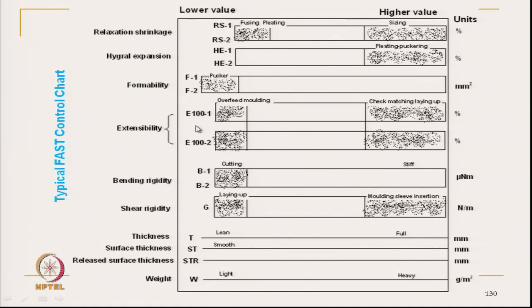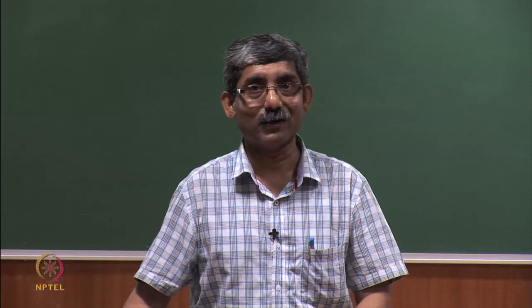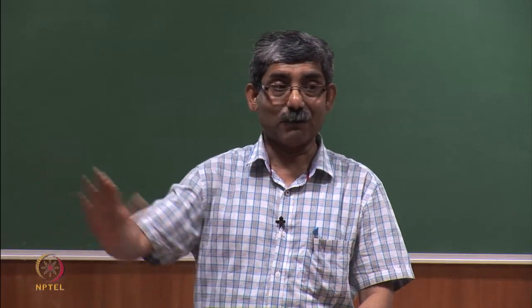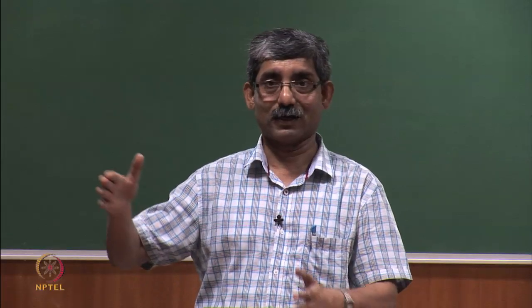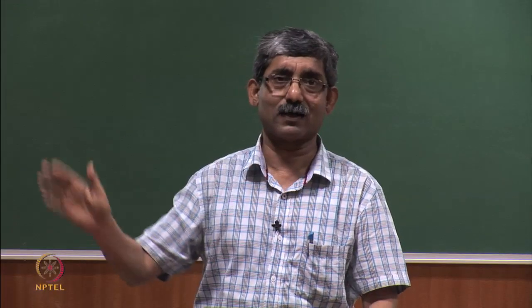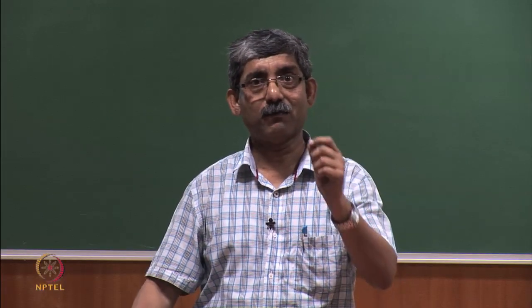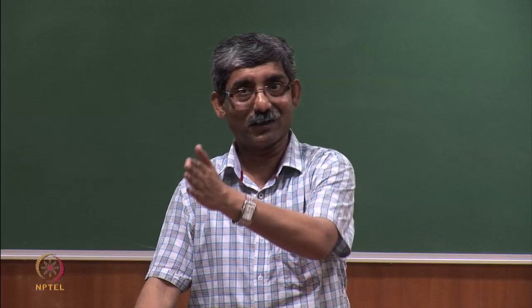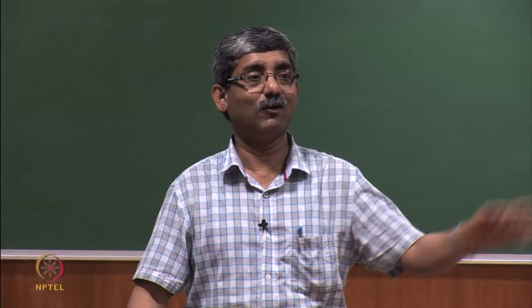Extensibility E101, if it is low, then there will be an overfit molding problem, and if it is very high, say if it is extensible, then there is a problem of check matching in layup, meaning during automatic cutting in the garment industry, the check matching will be a problem, because a large number of layers are laid automatically, and if the fabric is extensible, that means the check matching, if it is a checked fabric, then there will be a problem.